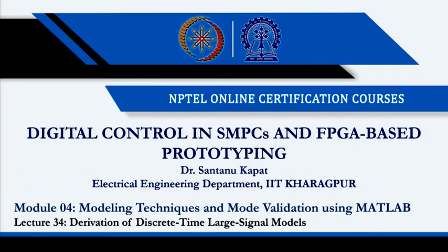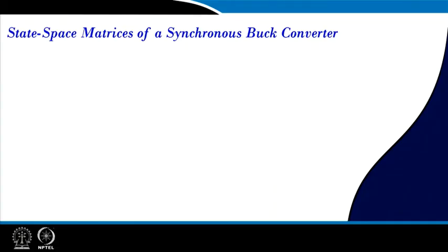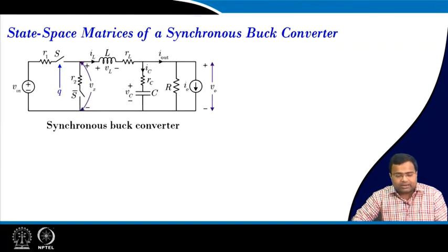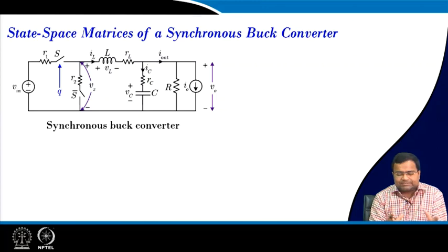In this lecture we are going to derive the complete discrete time large signal model. So, we will discuss first discrete time modeling in DC-DC converter that we started in the previous lecture, and then we want to derive the complete discrete time large signal model. First, if we take a synchronous buck converter, this is the circuit diagram, more or less a practical synchronous